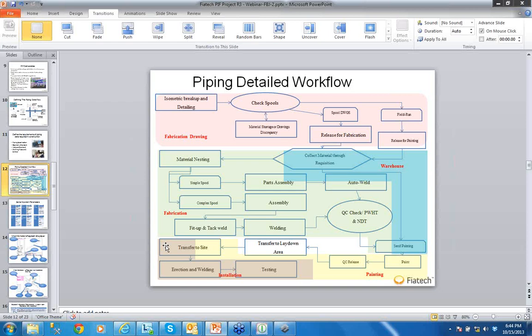If we want to follow their isometric limit, we will end up with additional cuts and redundant welds because of this limit in the middle of the pipe rack. And if we don't want to follow their limit, it means we will have to end up transferring material from one ISO to the other, so that we add pressure on the detailing office, however, minimize the amount of cut and weld, which is much more expensive than having to do it on a piece of drawing. So this is really a hassle for us.